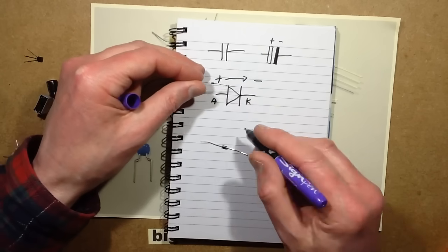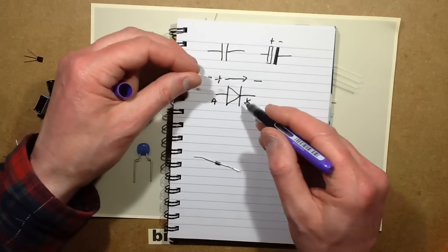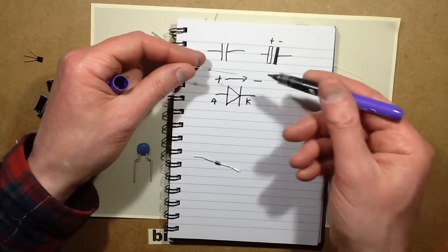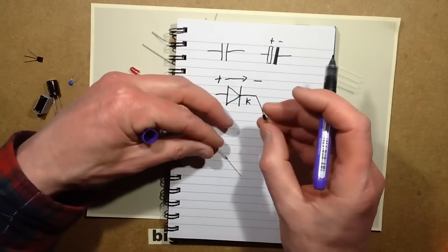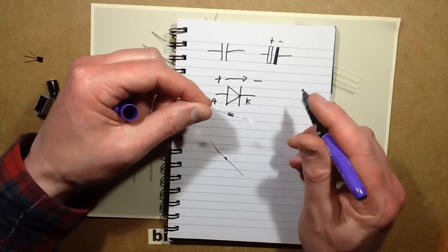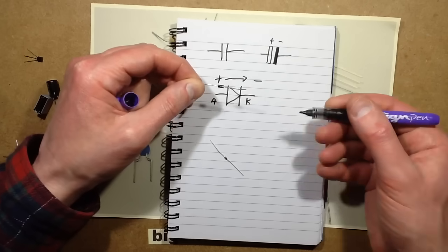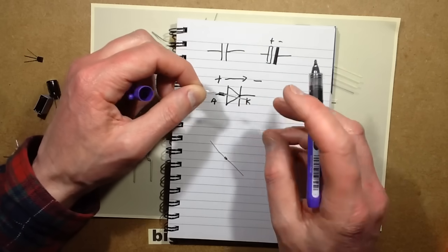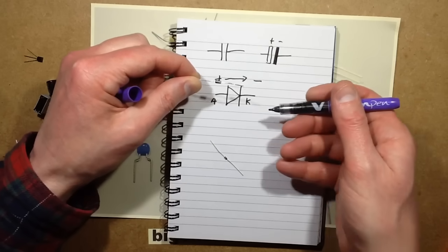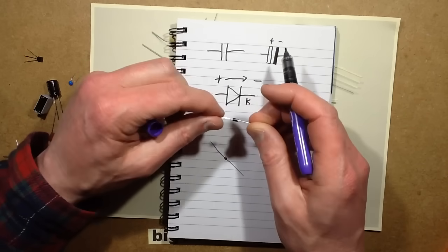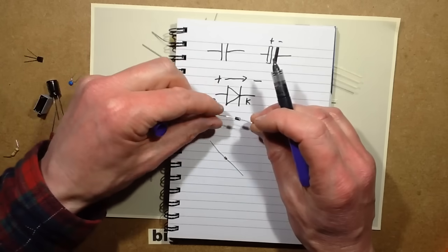And the other factor is the peak inverse voltage. That's the voltage it will block coming in the wrong direction. So supposing you did connect, well, this one is a 1N4007, it's rated 1000 volts. So that means that it will block 1000 volts going the wrong direction. But if you were to exceed that dramatically, it will avalanche and it will start conducting in the opposite direction. So you have to choose the correct diode for the job.